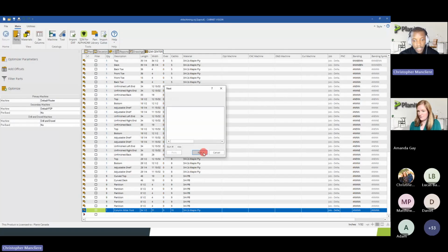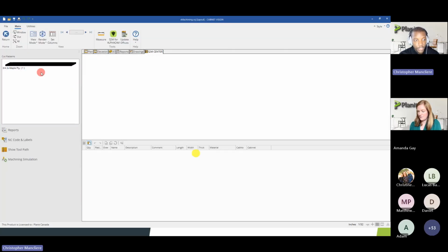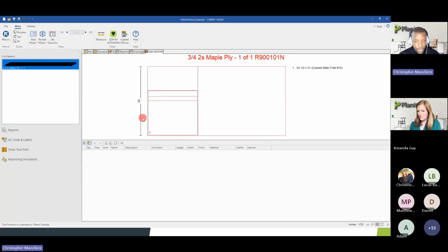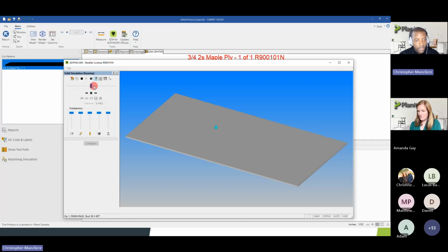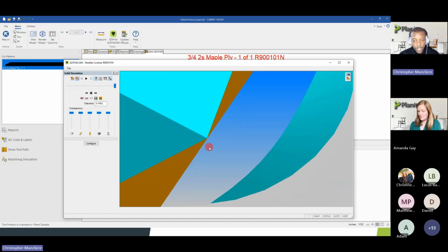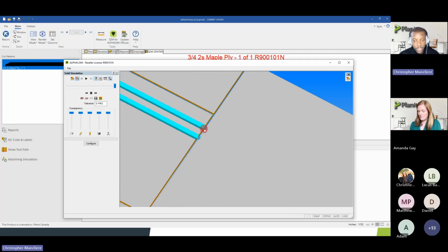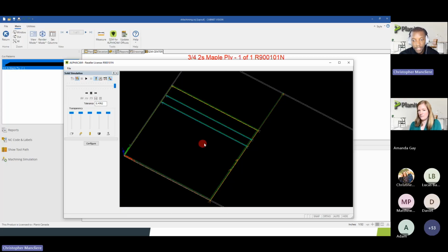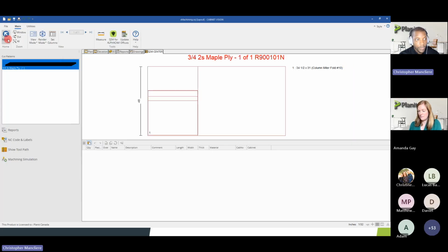So if I go and optimize my folded miter, now it's basically for my needs, it's only one panel where there's a bunch of operations just to fold all this on the CNC. It's the same size, it's all parametric, but if I were to just go, here you go. And the difference is this one doesn't go through because I just want to fold it on the CNC. And this doesn't need to increase the gap because it's a user added operation for it.